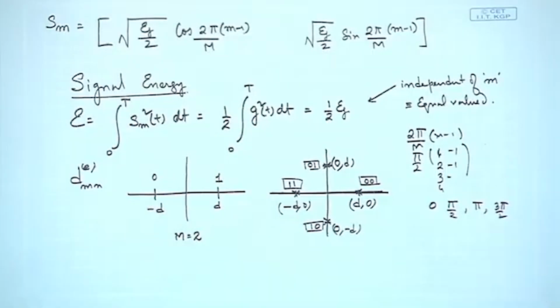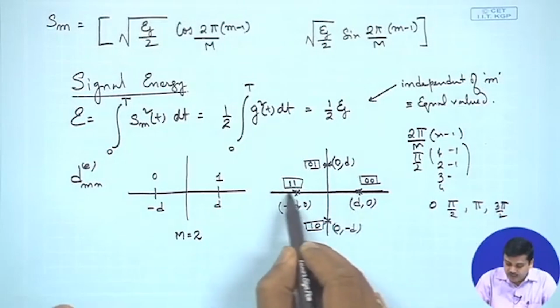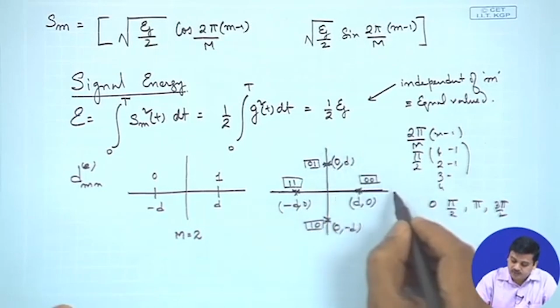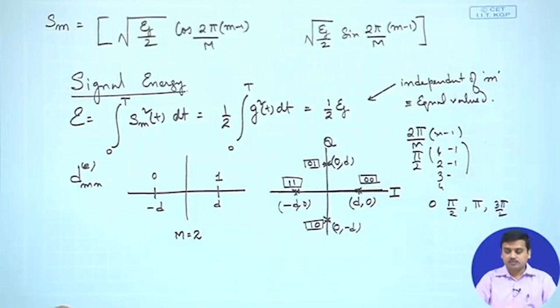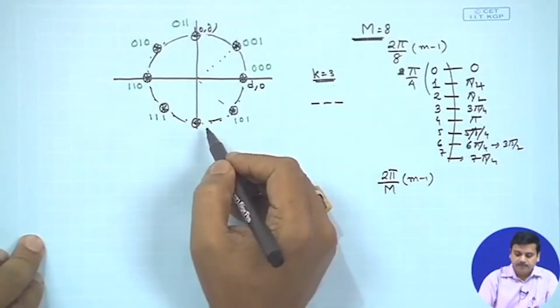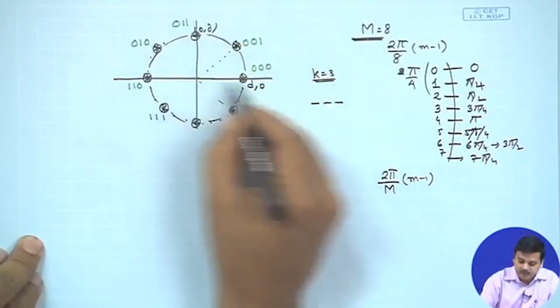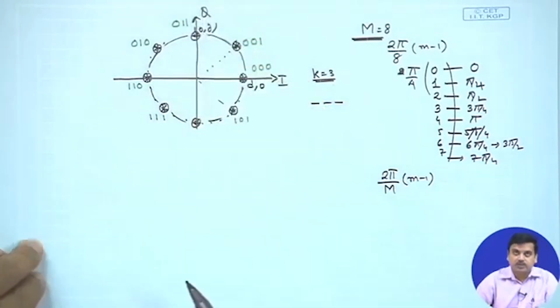Whereas, if you choose M equal to some higher value, as in this particular picture, we see that you have a cosine carrier and a sine carrier, that means the I axis and the quadrature, that is the Q axis. And if we move there, you have a similar thing, only that you have more values in it, but still they could be represented on the 2-dimensional plane.